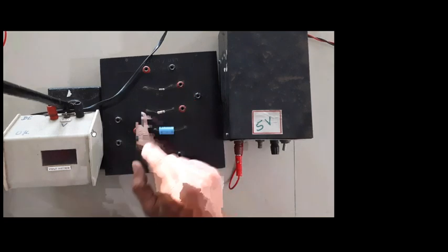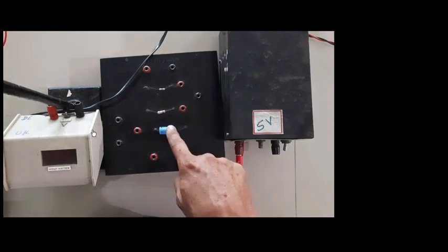If the resistance value is larger, the decay time will be longer. It is quite understandable: suppose you have a traffic road and you have a less traffic road. Less traffic means less resistance road, more traffic means high resistance road. So naturally, the more traffic road will take a longer time to reach from point A to point B. So if the resistance value is large, the decay time of the capacitance will be larger, and in the smaller resistance it would be less.